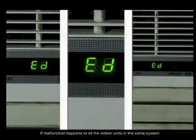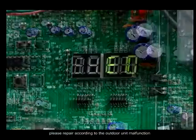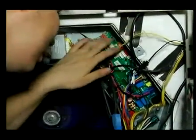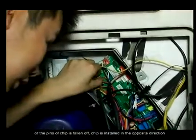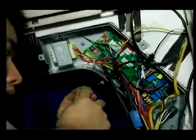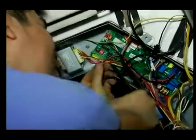If malfunction happens to all the indoor units in the same system, please repair according to the outdoor unit malfunction. During the above repairing process, before changing indoor main board, please confirm if chip of main board has problem, or the pins of chip are fallen off, or chip is installed in the opposite direction. The correct installation should be according to the direction of half round.